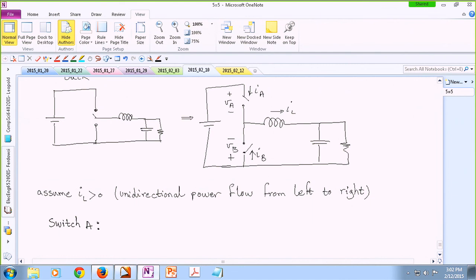Okay, now keep in mind the operating conditions of the buck converter. Switch is on, switch is off. When the switch is on, it is conducting positive current because it's the inductor current. When it is off, it is blocking your input voltage that is positive. So if you look at the operating conditions of your power electronic converter, you realize that assuming the inductor current is positive, your switch, when it is on, is conducting positive currents, and when it is off, it is blocking positive voltages of the source. So we need a single quadrant switch, a first quadrant switch.